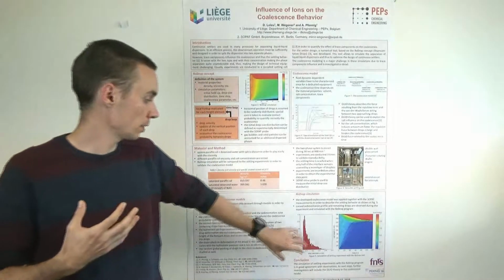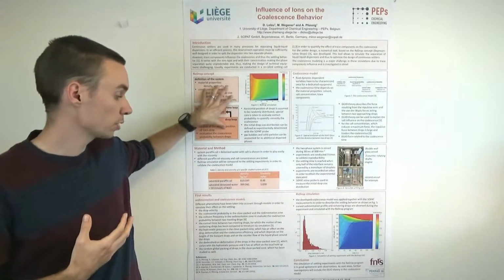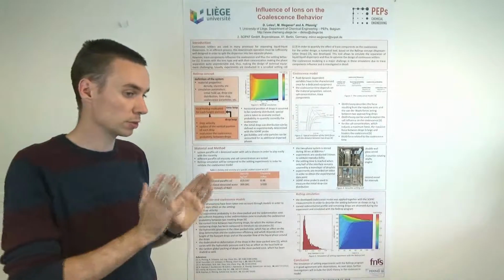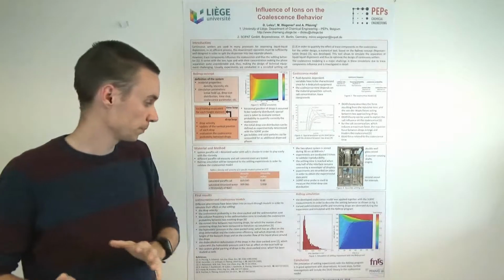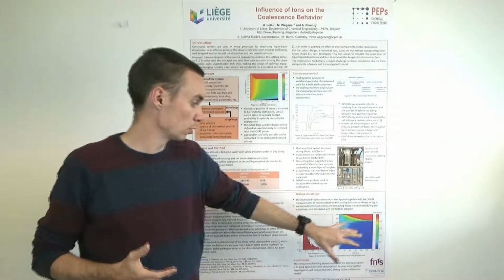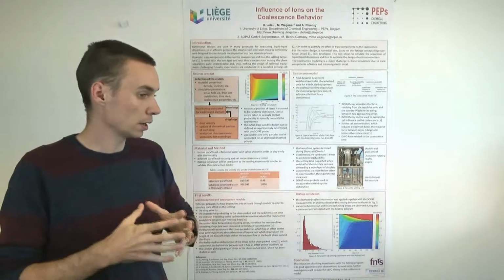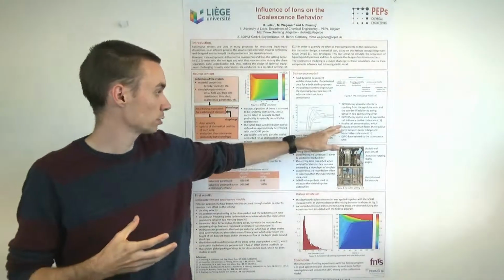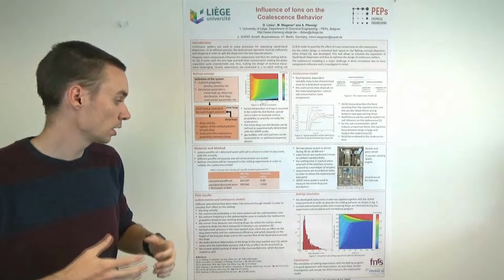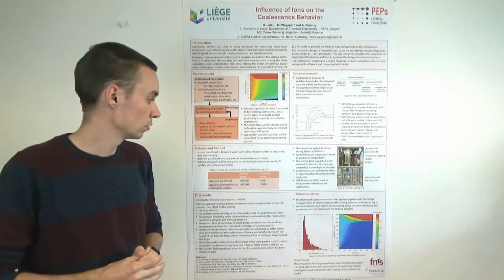Then I implement this drop size distribution in my ReDrop program, and I play with the coalescence parameters to fit the simulation to the experiment. And this is what it looks like. The color scale represents the local holdup of my simulation. The next step is to implement the DLVO theory in the coalescence model, and to compare the simulation and the experiment to validate the model.